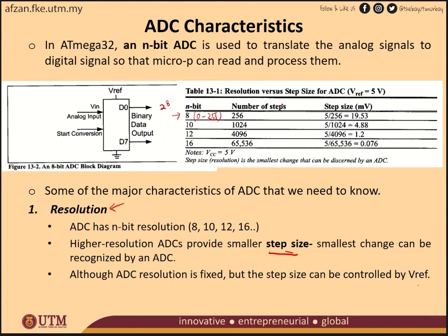So in order to get the step size, here is your VREF, and the step size is equal to VREF divided by your number of steps.